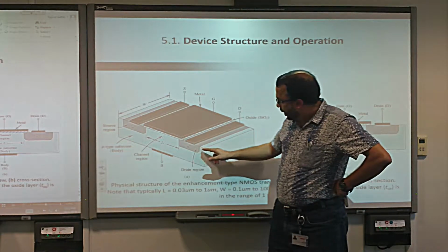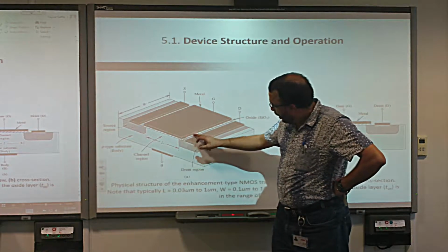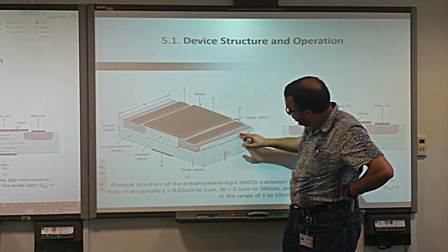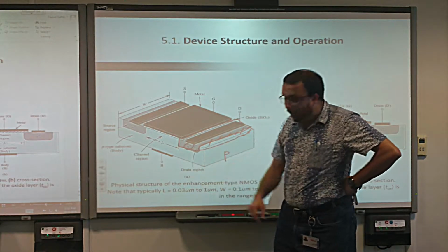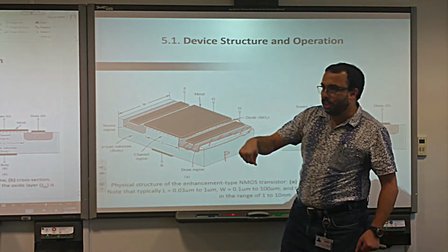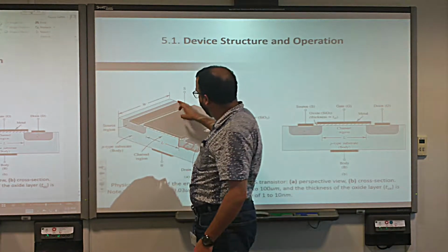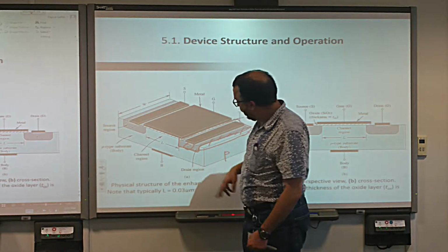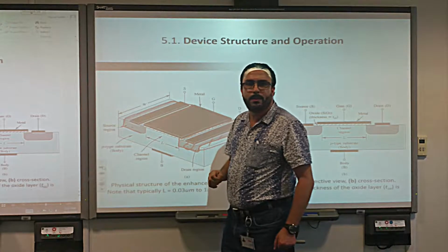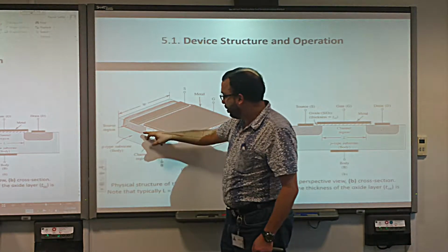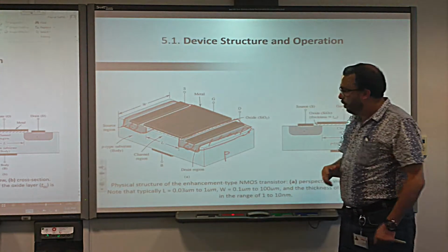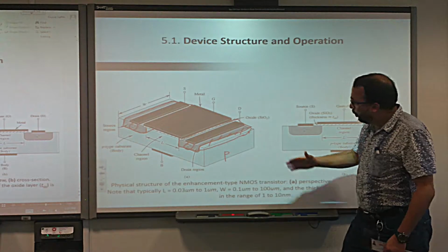On top of it, I doped or diffused two areas. This area is actually inside as well, a highly doped area. When we say N+, that means it's not only doped, but doped too much. This one, and another area on the other side, same thing. Doped excessively with acceptors or donors? Donors. Yeah, that's why they are n-type. But too much means excessively.